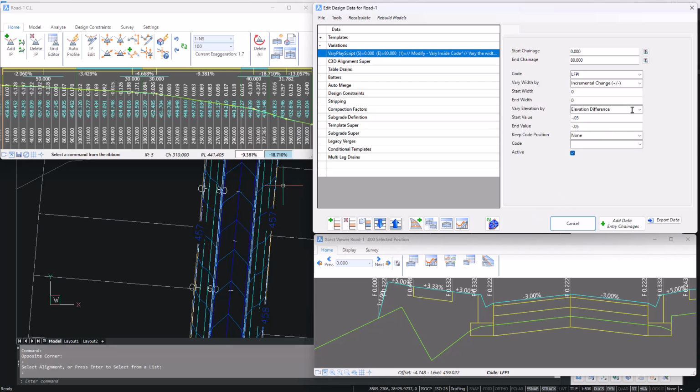And I can also set it with an incremental crossfall change. So it's currently at 2.5% coming down. I'd like to take 0.5% off that. So I'm going to say let's lift by 0.5% from this point. Okay, so that was 2%, so it's now 1.5%.